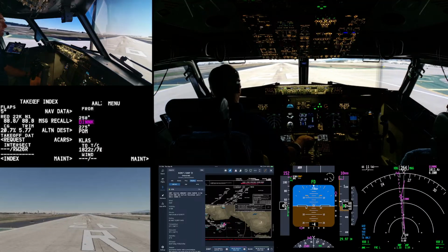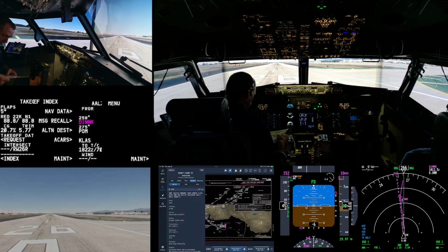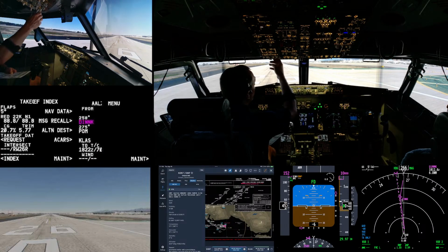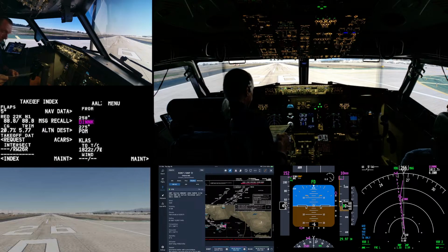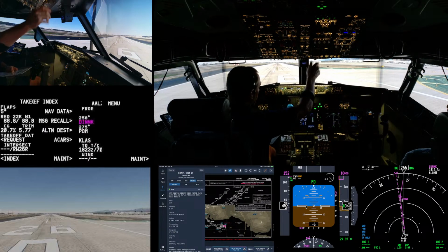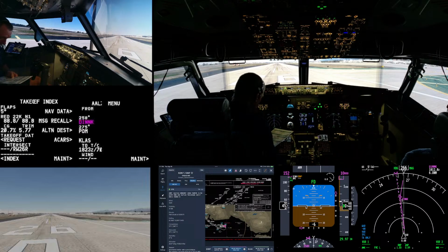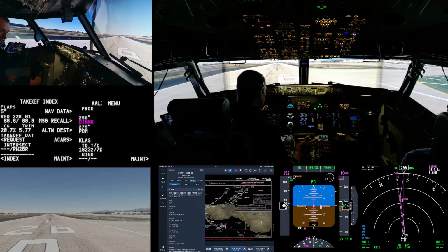On runway 26 right. Alright, so before takeoff, attendants have been notified. Exterior lights are going to be on strobe. Landing lights are on, runway turn-off lights are off. Engine starts on continuous. Auto throttle is engaged. Transponder TARA, parking brakes released. Throttle at 40%. Let's do it. And we're looking for stabilized, and they're good.